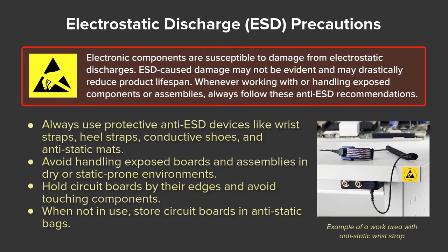Electronic components are susceptible to damage from electrostatic discharges. ESD-caused damage may not be evident and may drastically reduce the product lifespan. Whenever working with or handling exposed components or assemblies, always follow these anti-ESD recommendations.